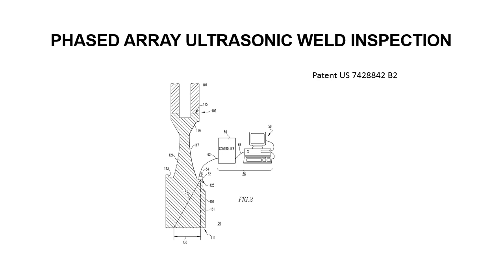Where if you and the wife or girlfriend or significant other are going to have a child, and you go in and they do the ultrasound on her, same thing, except with a weld. It's just, instead of giving you just a spike on an indication on a CRT, here they're giving you an image, and it'll give you an image of what's in that weld. A lot of this is due to the ability of computers to process massive amounts of information.